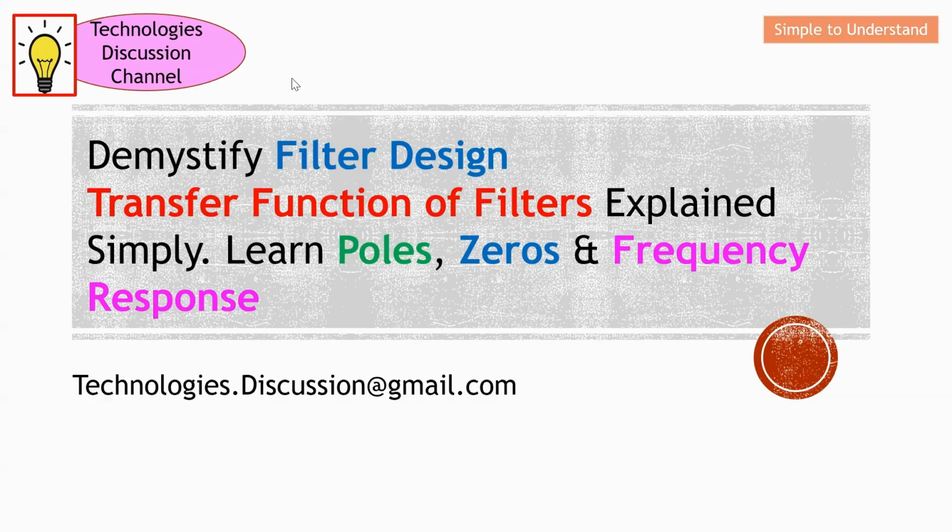For this video, I'd like to continue the discussion on filter design. In the first portion of this video, I will explain what a transfer function for a filter actually is. In short, the transfer function explains the relationship of input and output. This is essential for filter design. For example, after the filter, some of the signal will probably need to be passed, and some of the signal will probably need to be attenuated. Therefore, with a transfer function, we are able to describe them in a mathematical way. So this will be the first objective of this video.